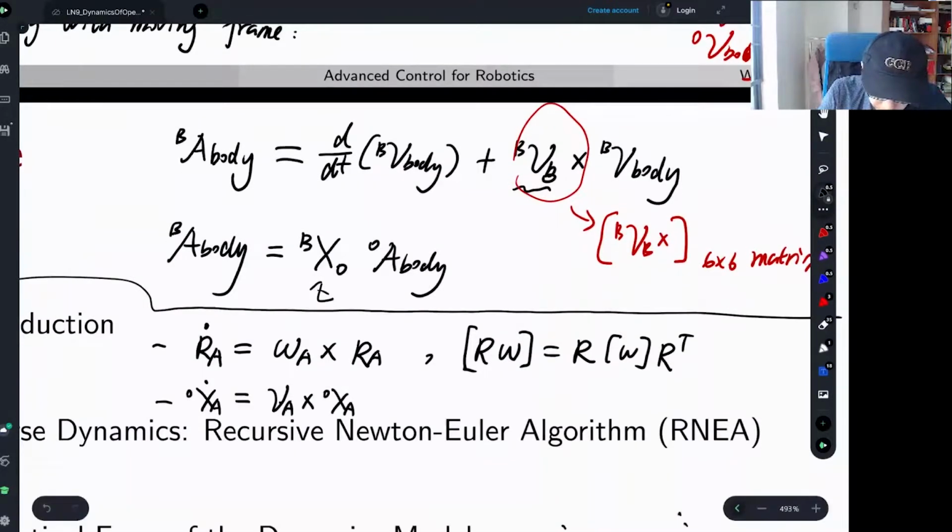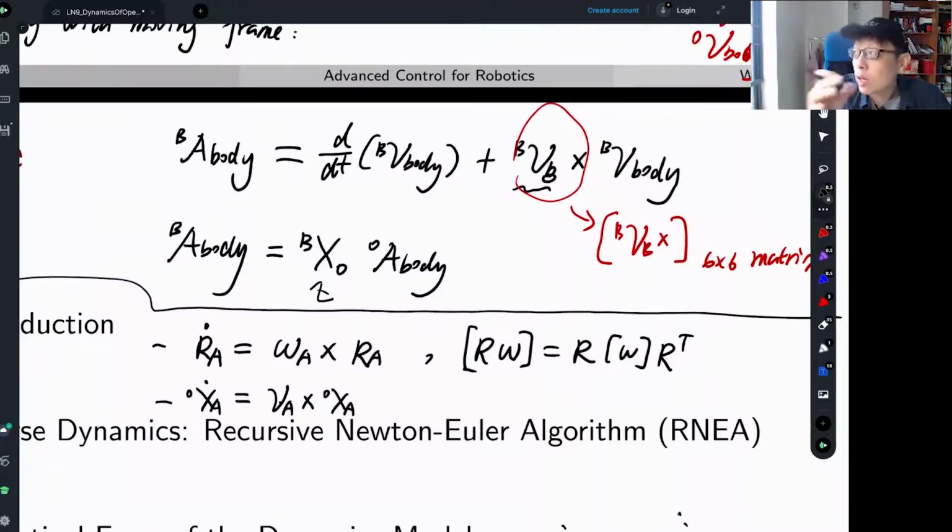Okay, and when we write like this, the R_A is not an operator. It represents the pose of A. In particular here, X_A, although I constantly tell you this is the change of coordinate for twist because that's easy to picture, right? Actually, its column of X_A in O is the motion basis vectors, expressing the elementary motion with respect to the coordinate frame A, right? And the first column is the rotation, unit speed rotation about the OX axis. Okay, it has physical quantities.